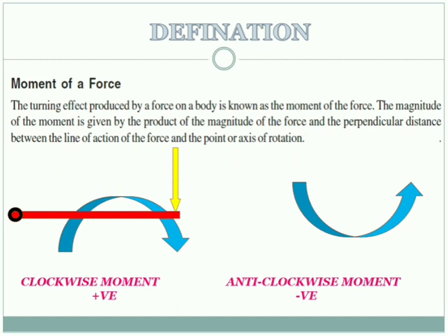Now if the force has a value of say 10 Newton, and the beam is of length 5 meters, then what will be the moment? Magnitude of the force 10 multiplied by length of the beam 5: 10 fives are 50. And the beam is rotating in the clockwise direction, hence it will be plus 50. So with this illustration I have tried to once again elaborate the definition of moment.